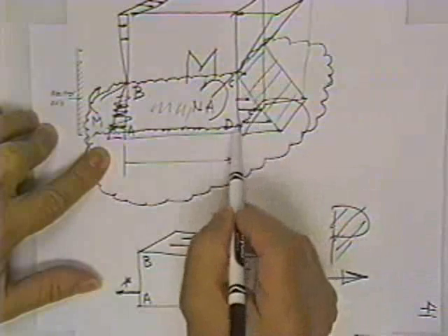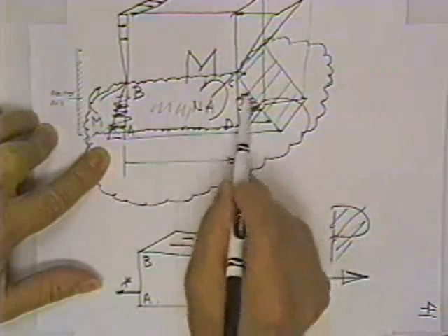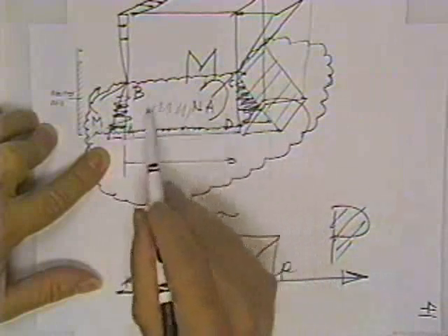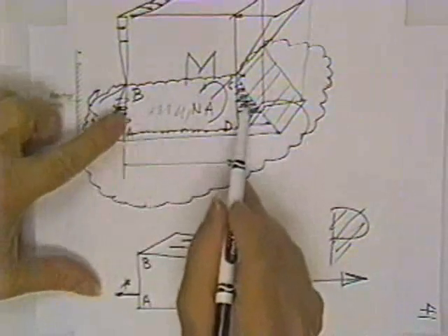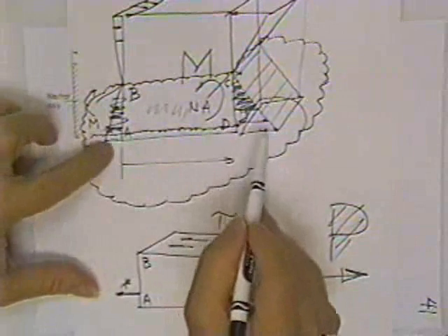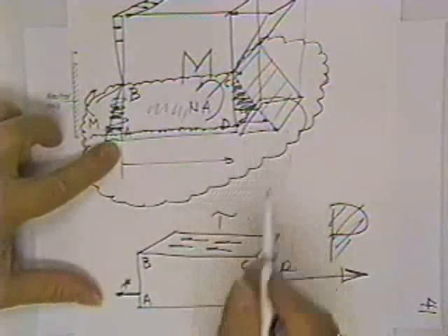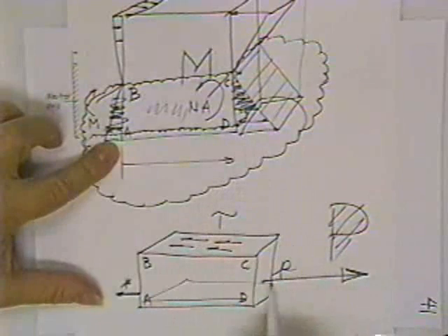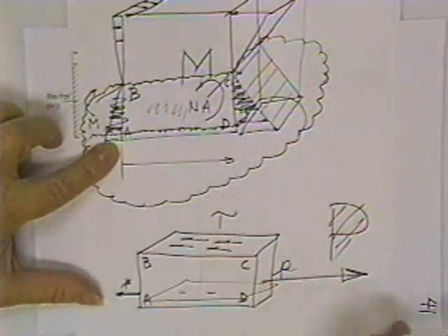And the reason is all of this imbalance here is no longer on the free body. These two imbalances no longer are in effect, and only this little imbalance is in effect. So on that face lower down here, you would see much smaller stresses than you see at the neutral axis.